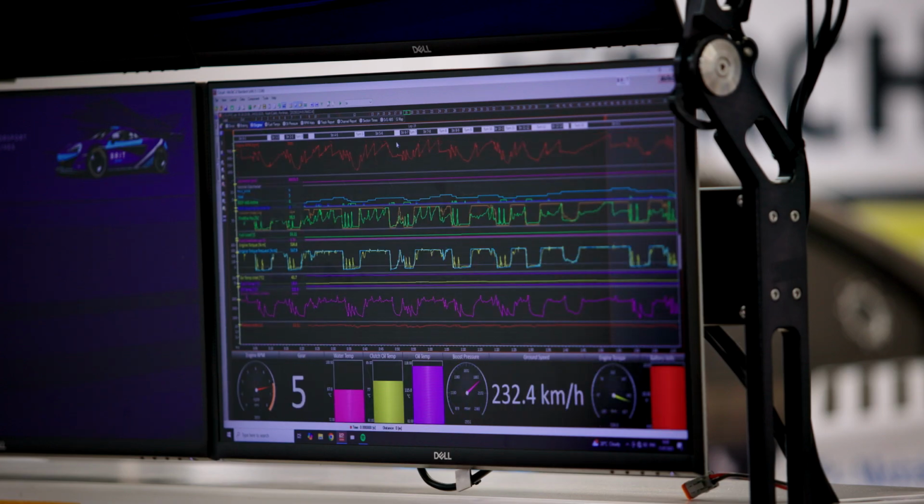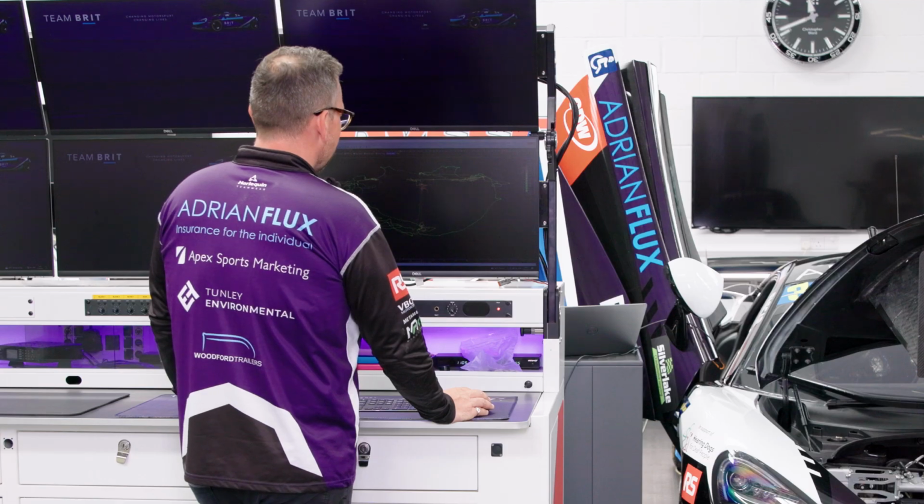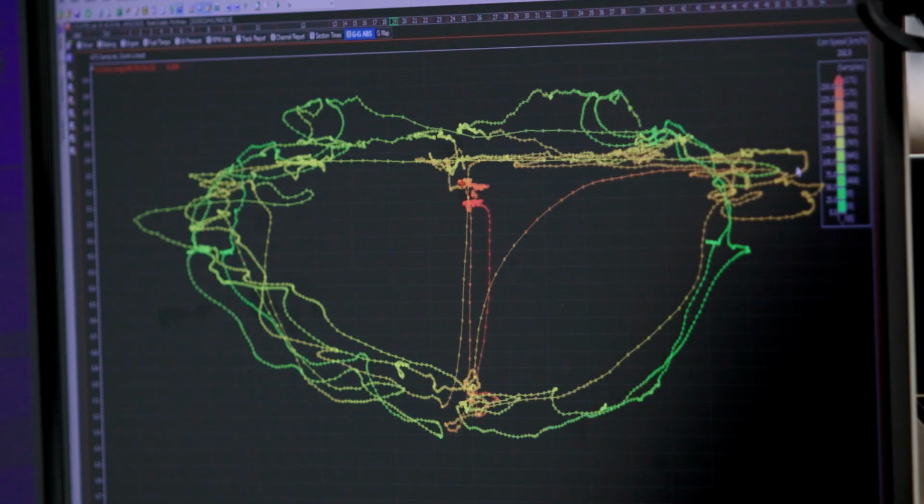One of the ones I really like is the ABS plot. So what we see here across the course of a lap is all of the data points built up based on how much load we're putting in the car. So when the car's at rest, the accelerometers would be reading the center here, and when we go around the left-hand corner, the accelerometers are going to read over to the right-hand side here, indicating that there is some high load right-hand corners on the circuit. That's where these data points are.